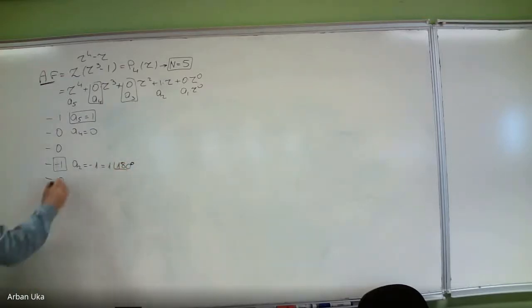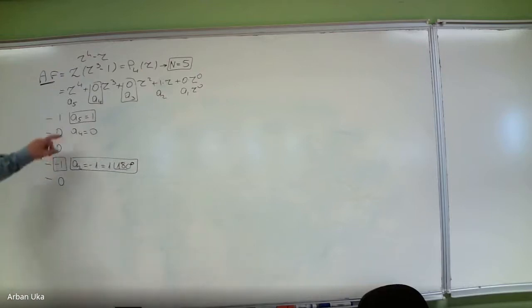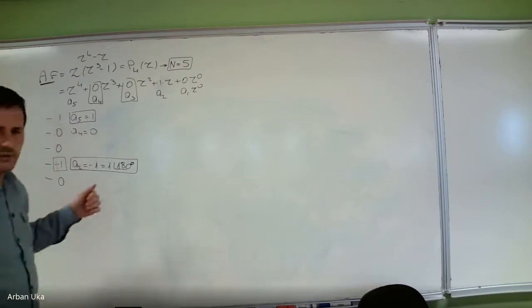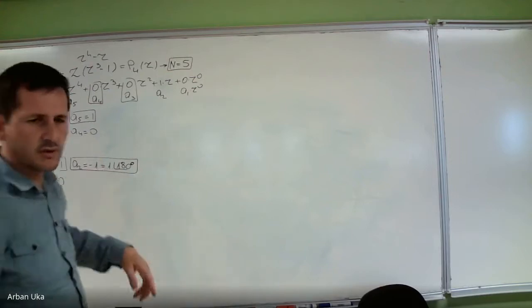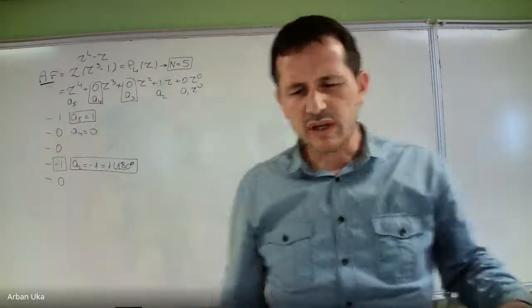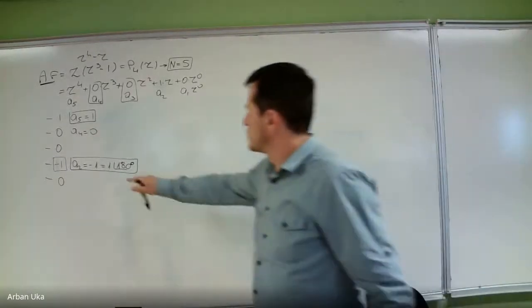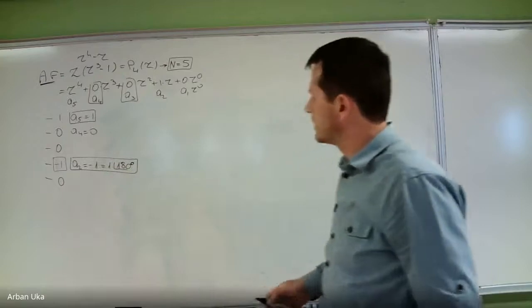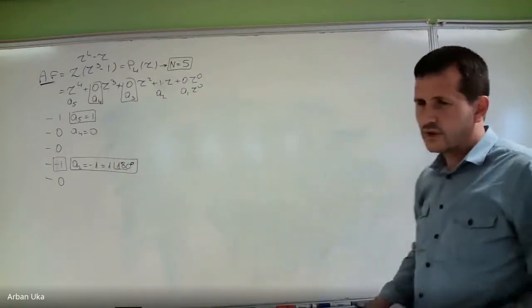Okay. So what does this mean? This means that we can have an excitation of the current in this element with some sinusoidal wave, and in this other element, it can still be the same sinusoidal wave, but it can be 180 degrees out of phase with respect to the other one. So these two statements are equivalent. You can choose either one, but you are right. It should be minus 1.